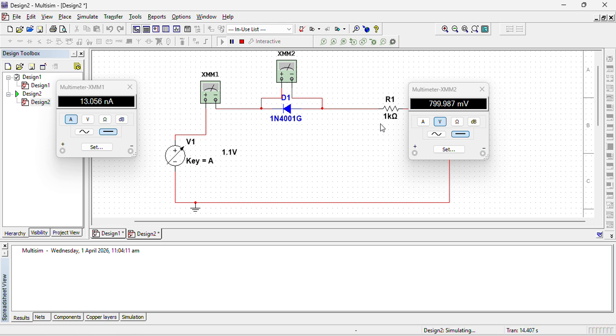So this is how the diode blocks the voltage in the reverse bias direction. Let's say we have supplied 10 volt and the complete 10 volt appears across the diode, and there is a very minute amount of current, which is nanoampere. If we compare it with forward bias, there after around 1 to 2 volt we had a current of milliampere, which is sufficient.